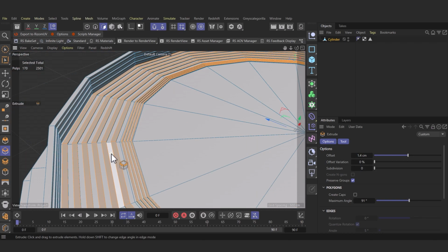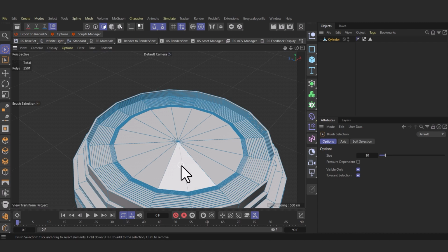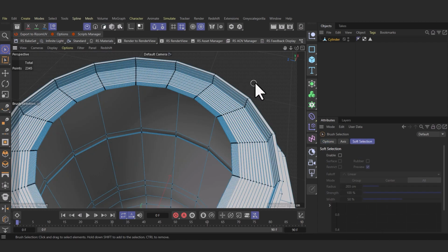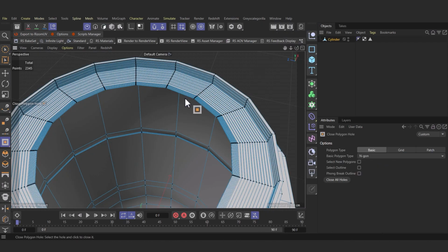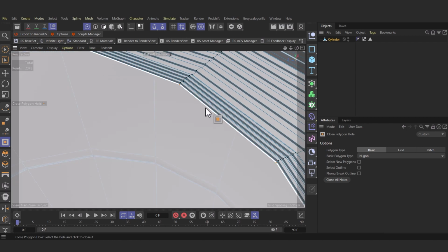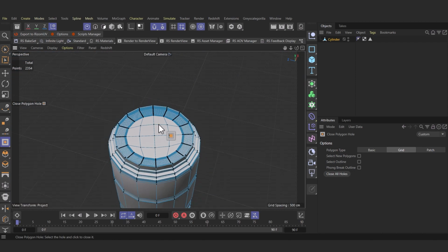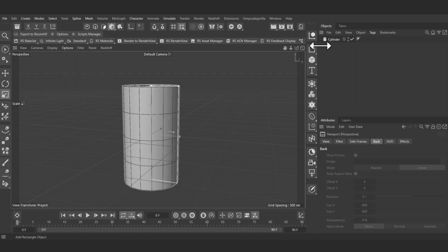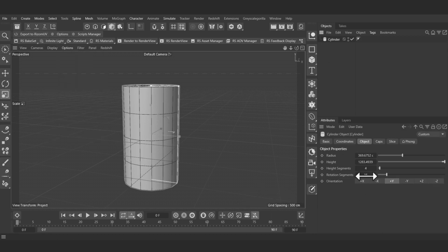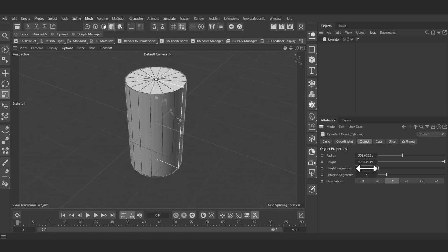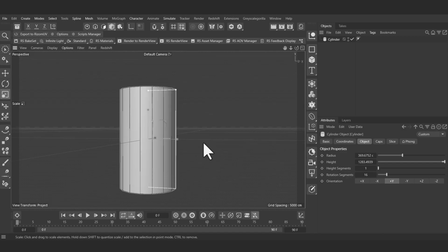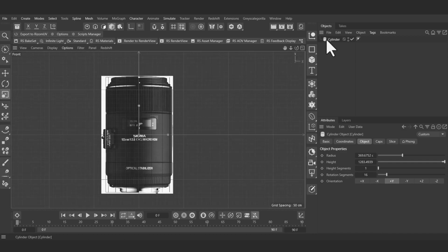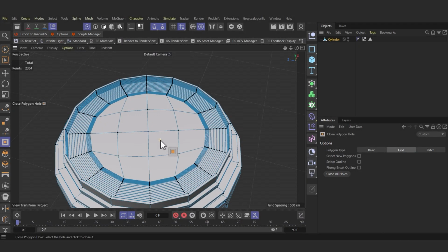As you can see, this area does not have quadrangular polygons. That's why I completely erase it and complete this area again with the close polygon hole tool. Let's be careful to select the grid option in the settings section. A very important issue that came to my mind now is that if you consider the cylinder parts at the beginning of your modeling as numbers that do not have good coefficients for making quadrilateral polygons like this, when you want to build an environment, you face serious problems and you have to waste a lot of time to manually reconfigure. So be forward looking.